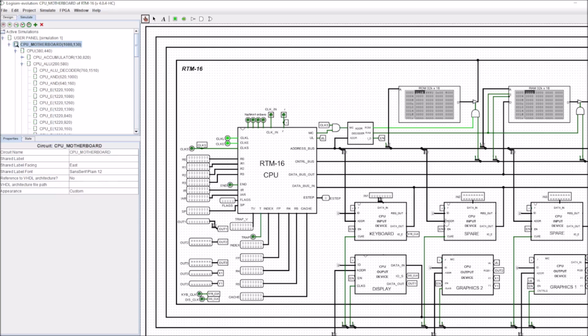The select would choose between whether it's going to be add, subtract, multiply, division or square root in the floating point unit. So it would have to pass all these values over, and then once it passed over it would have to take the value from the card back onto the bus. So it was going to have to use more clock pulses in order to do that, and it would be a little bit slower and a little bit more cumbersome.